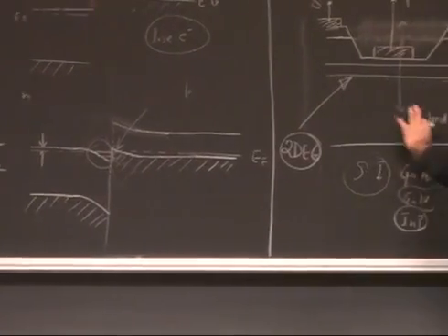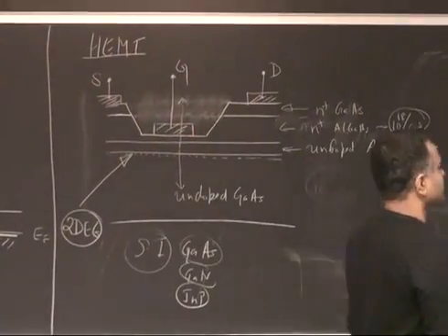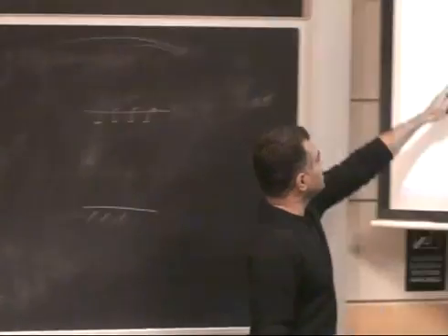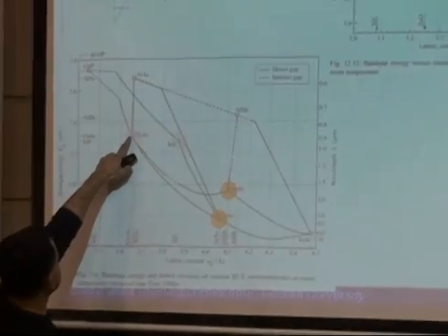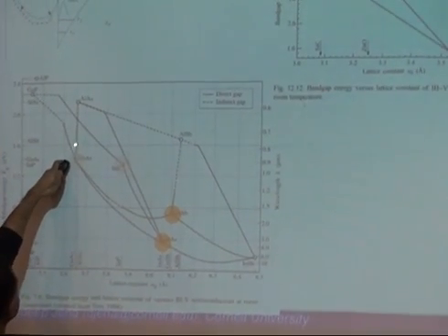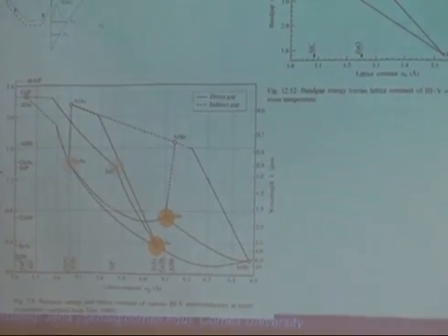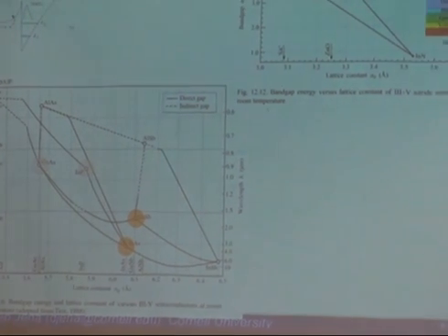So let's look at the choice of materials. We are looking at gallium arsenide, and say 30% aluminum gallium arsenide, right? So we look at the band gap, gallium arsenide, 1.4 electron volts. 30% AlGaAs would be kind of somewhere there, right? That's the band gap, almost lattice matched.